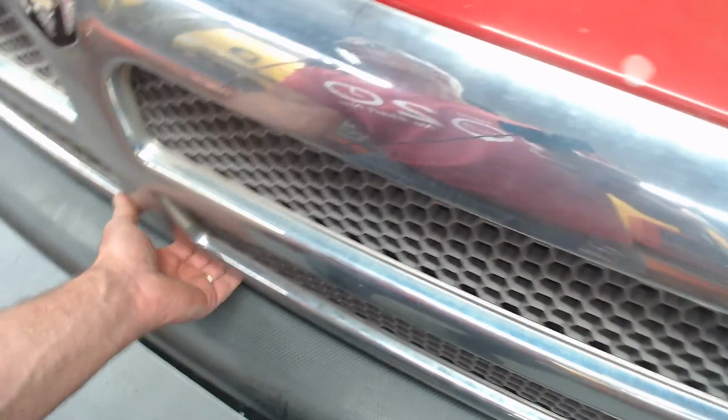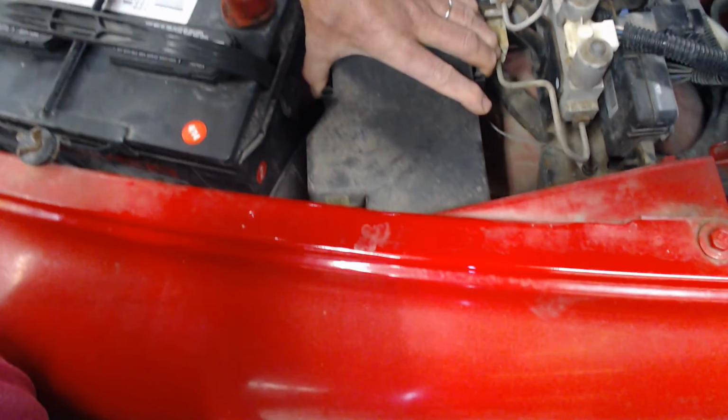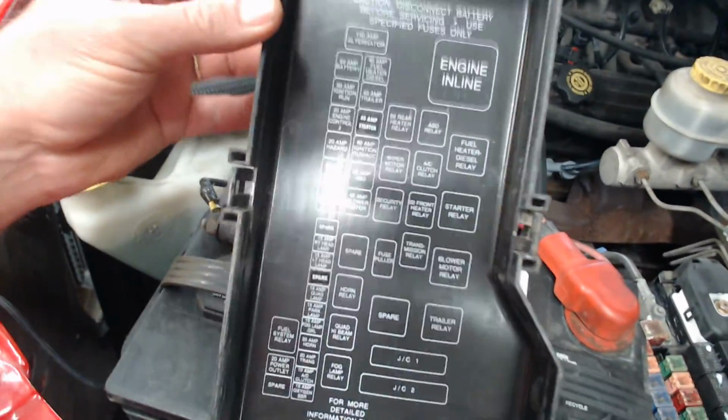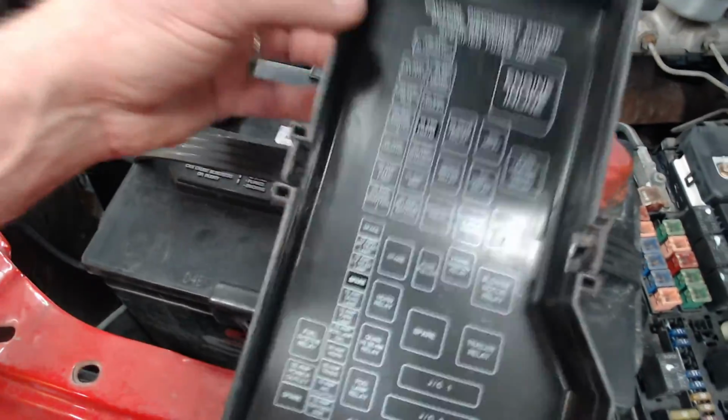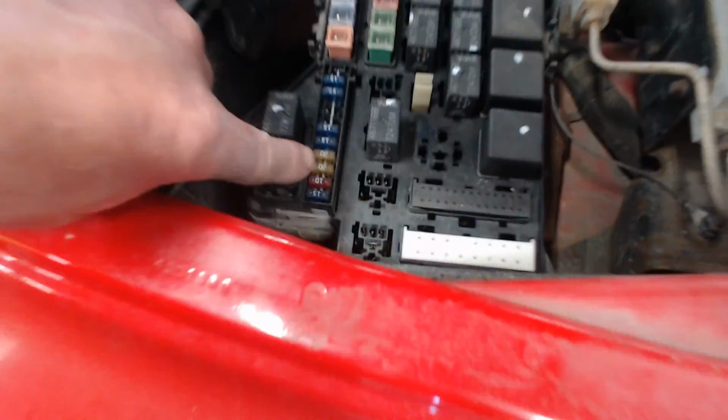So I'm going to walk over here to the car, and again, sorry for making you dizzy. I'm going to open up this guy, and here's the power distribution box over by the battery. I've got to squeeze these 2 clips and pull it up, and on the underside I've got some fuse and relay detail. So I know I've got a fuse 3 20 amp, probably one of these 2 right here, or it could be one of these 20 amps here.